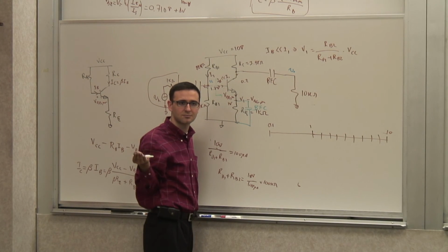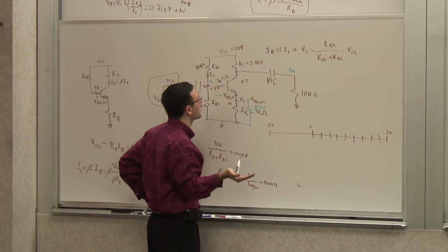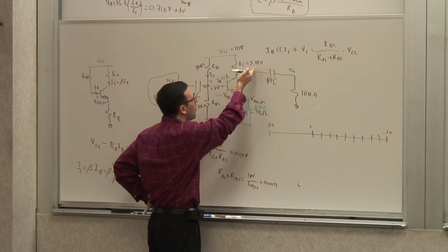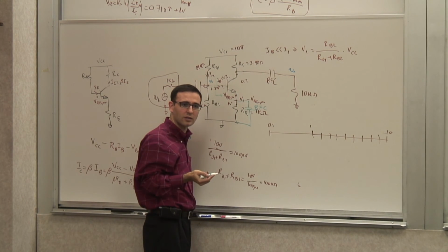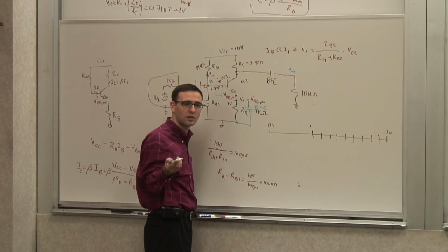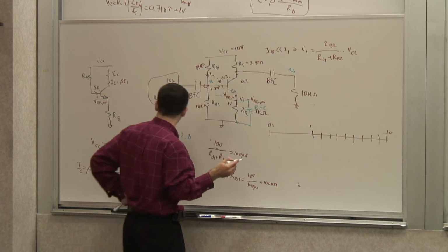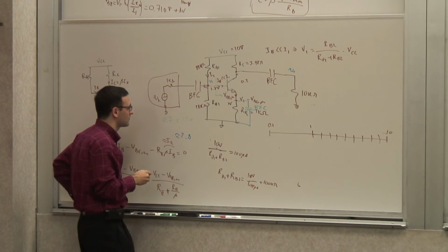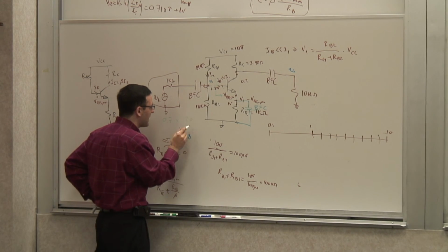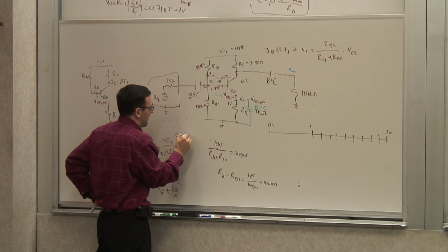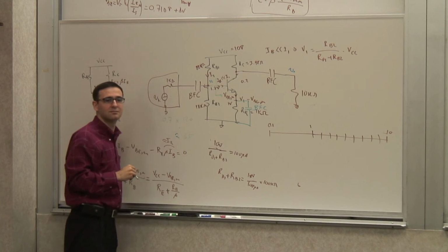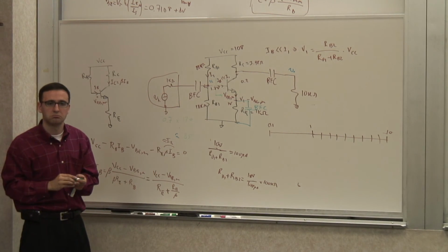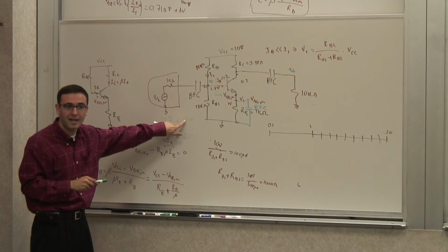Approximately 3. So it's 3 kilo ohms times 40 millisiemens, so it's 40 times 3, it's 120. So that's times 120. So what is that, with 0.7? It's about 80 something. I would estimate 85. That's fair. Although I lost on this one, I gained a lot more on this one.